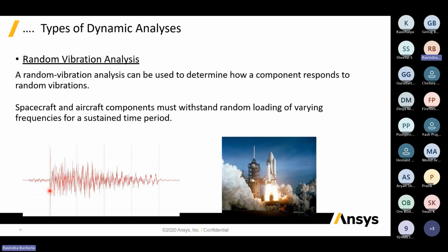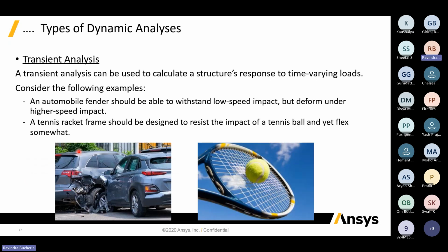The second case that we discussed is basically very simple vibrations, where we will be measuring the frequency versus displacement. But if the amplitudes are very high, then we will go with the power spectral density method and we will be analyzing if there is any probability of failure because of these external frequencies and natural frequencies. Okay. So these are the three different vibration analyses that we will be having.